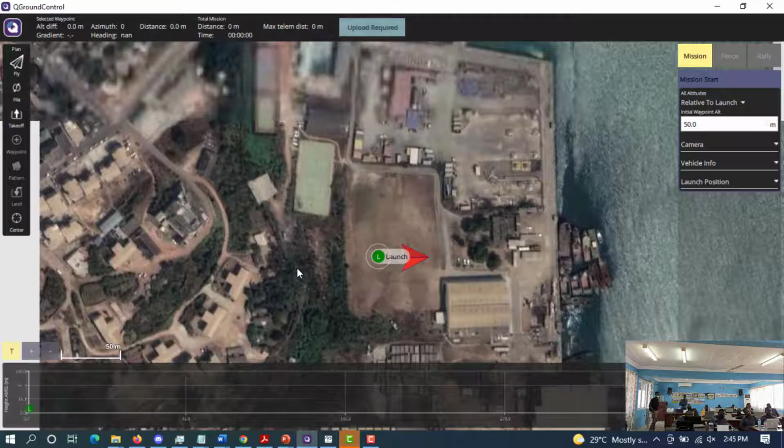Now, let's say that I'm done with my few clicks. I kept my altitude at 90 meters. This is my last waypoint, and this is where I want to come and land. The landing component is made up of two components: the landing sequence, and then the landing stop. So let's say that after this waypoint, I want to bring the aircraft back and land.